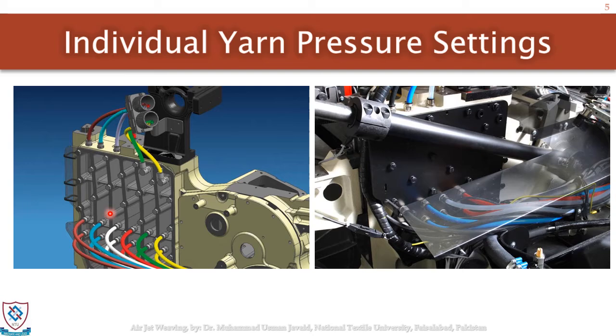There is a possibility that different types of yarn require different initial acceleration or different pressure to be accelerated in a different way. If we use the same tank, the pressure will be the same and the same amount may not be applied on the different types of yarns. To cater to this variation, we must have different channels with their separate individual tanks.